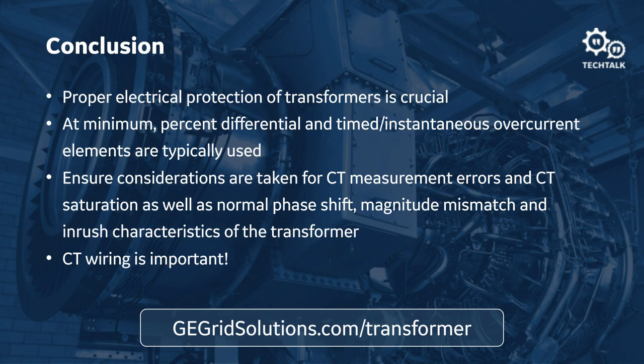So in the general transformer settings in the relay, in that first screenshot I showed earlier, for each winding there's a grounding setting where you can select whether the grounding is within zone or not within zone. If you have a winding that's grounded in any way, then you should select within zone. In that case, the relay will perform zero sequence removal on the winding currents of the grounded winding. The formula that's used depends on the winding configuration, but these are all listed alongside the phase compensation equations in the user manual.